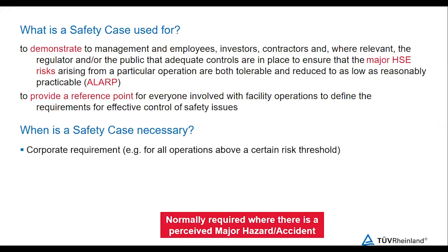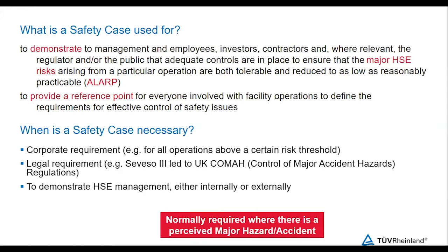Sometimes the safety case is a corporate requirement for some corporates like Shell, BP, whatever. Regardless of the country they are operating in, they require all their facilities to have their own safety case. Sometimes it's a legal requirement, like Seveso 3 in Europe, which led to the UK COMAH and safety case regulations.